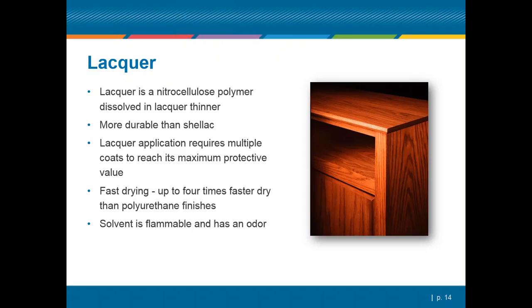With lacquer, although we're not talking about rag issues here, lacquer thinners are a very flammable solvent. They have a relatively low flash point, so they can flash relatively easily. Good air movement and so on is very important anytime that you're using these finishes, just to make sure that you're not building up enough of the solvent vapor to create any kind of flash point. Lacquers are more durable than shellac in their nature. That normally requires multiple coats to achieve the finish that you like to achieve.